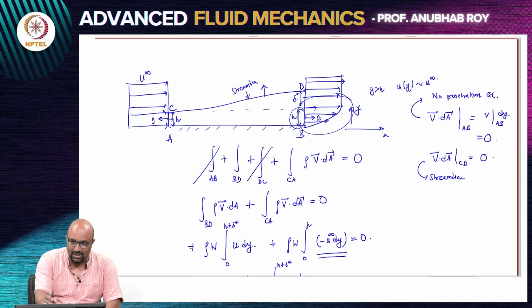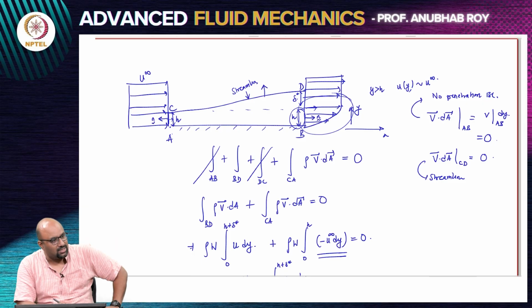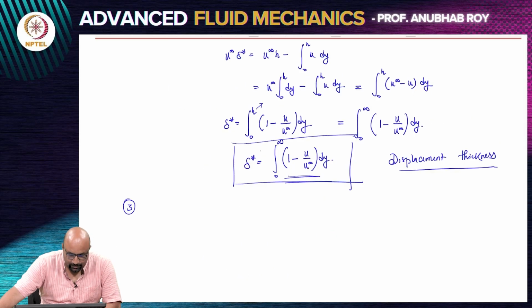So, in that displaced streamline, we know that there is going to be a certain amount of deflection to compensate for the fact that I have slowed down. So, I need to go through a larger cross-sectional region. But what about the amount of momentum that I brought in? Would that amount of momentum be the same just because I have now drawn that the mass is going to be conserved if the streamlines get displaced? So, let us measure the momentum inflow and outflow.